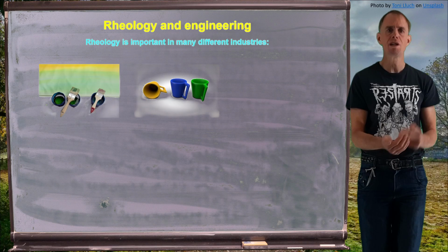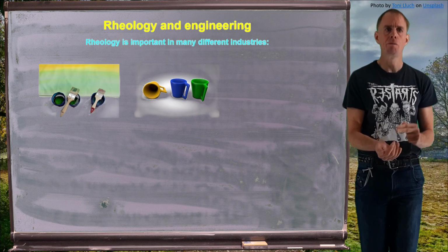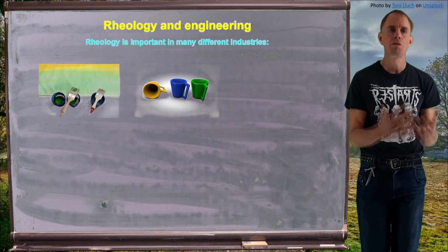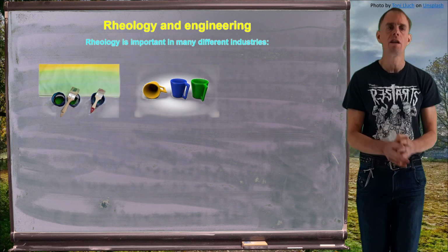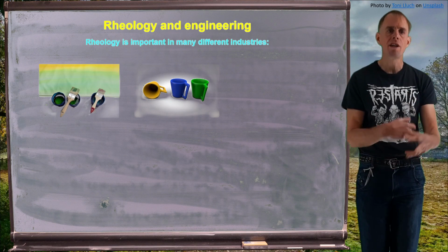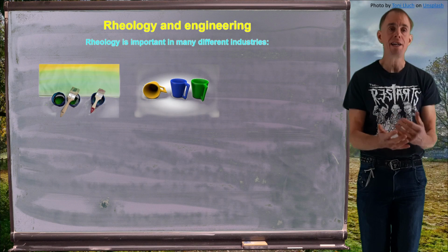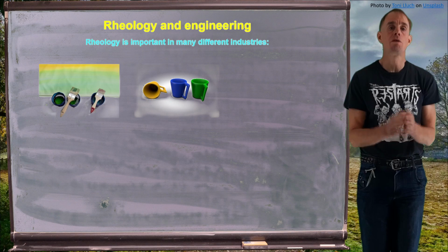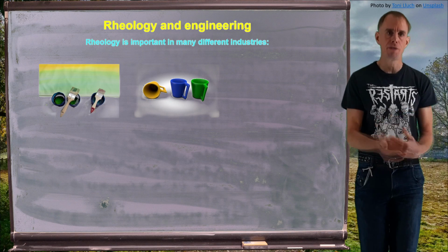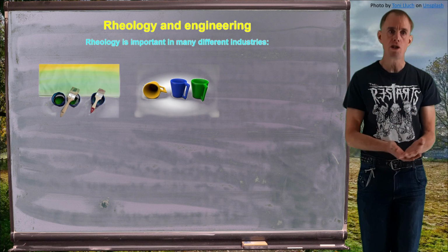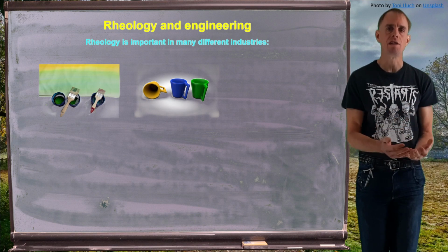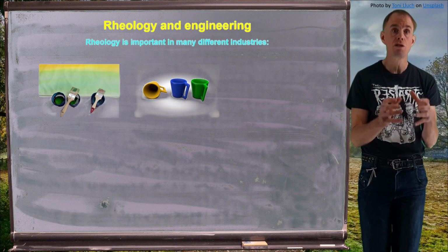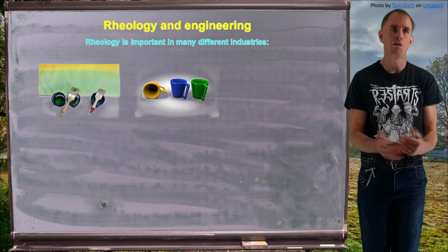We want the material not to shrink too much when it cools down, and we want to make sure that there's no residual stress within the material that can give rise to premature failure of that product later on in its life cycle. So, in order to understand the stress behaviour of such a material and its flow behaviour, we need to be able to understand how the molecular architecture of the polymer affects the flow, affects stress storage, and then how that stress is then released, and then make a judgment as to whether or not those stresses are going to be retained residual stresses in the product, possibly leading to problems later on, or not.